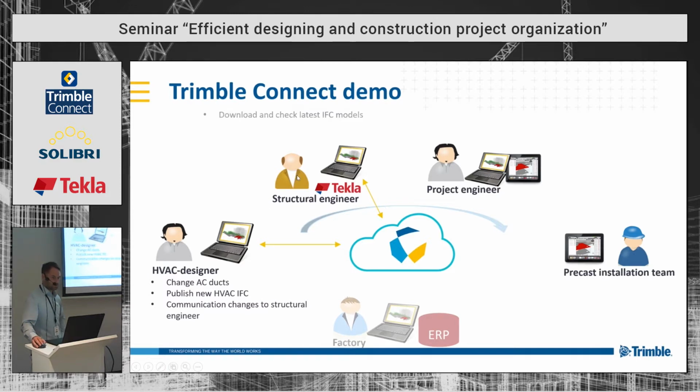And of course, what happens then, the structural engineer who's working in Tekla Structures can download and check the latest information, use the change management tool to compare IFC files, for example, make some changes to the structure if needed, and then publish it back to the Trimble Connect cloud.